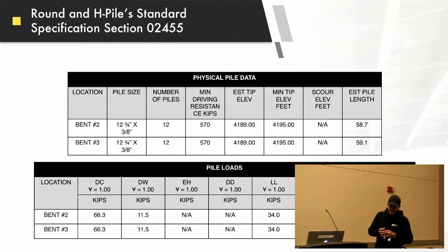Bore logs are a good thing to look at to understand what the subsoils are, but I've been on projects where they had bore logs and we're 50 feet away, and because of the terrain and everything, the bore log wasn't even remotely close to what we were driving in. And so as the hammer is driving pile, it's not something that you can just sit in your truck and say, yeah, it's getting done.